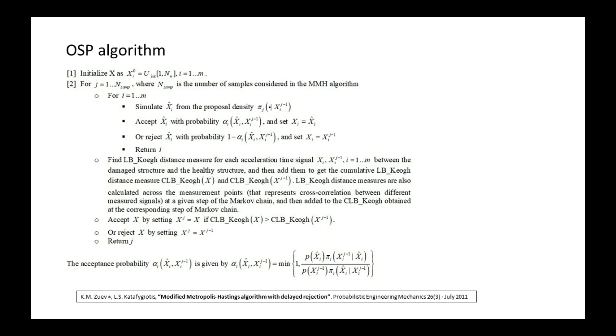If you have an FE model with 50 nodes, the sensor can be located at any position from 1 to 50. So they are non-repeatable random integers, and we generated non-repeatable random integers as x. Those are the unknown random variables, and we use the cumulative KL distance as the acceptance criterion of the Markov chain. Using this algorithm, we found the optimal location of the sensor.